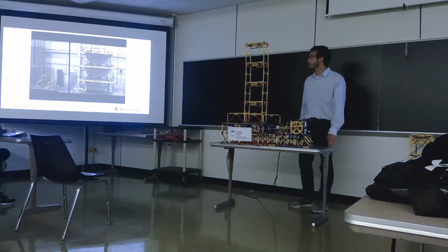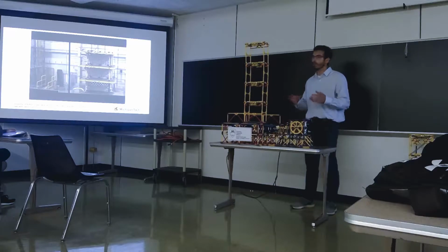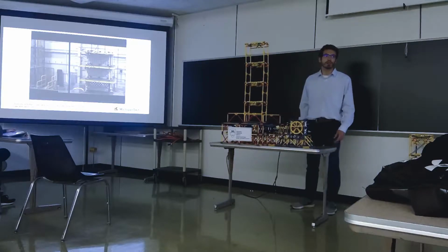So this is the University of Buffalo, and that's a frame that you put in a building to resist earthquake or other lateral loads like wind, and it's meant to dissipate energy like damping in the form of the steel plates that are in the center. So this is just one example.